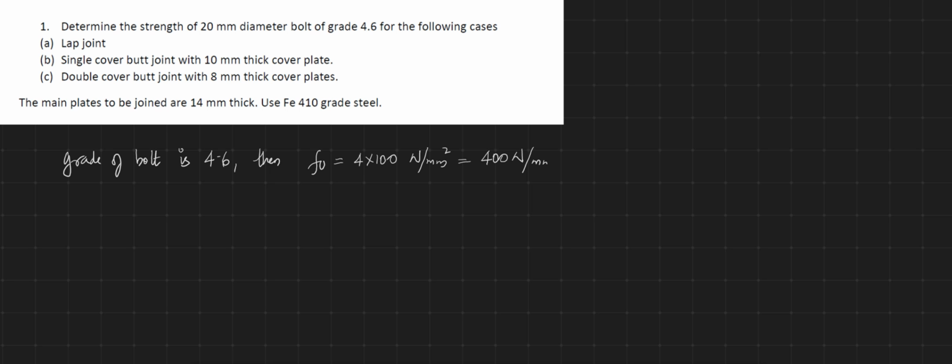The yield strength Fy of the bolt will be 400 into 0.6, that is 240 Newton per mm square.